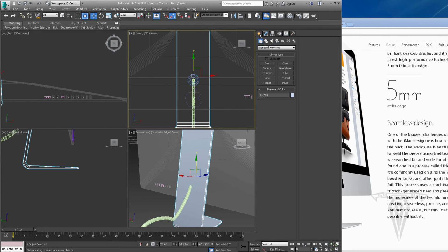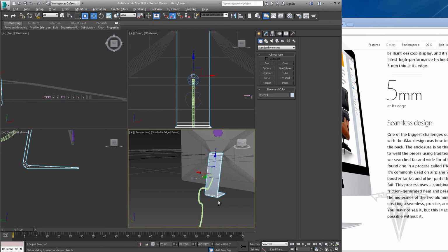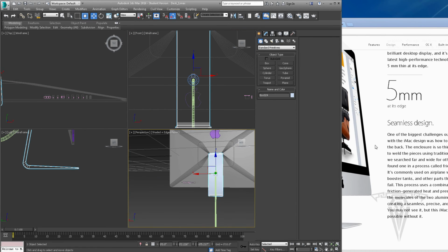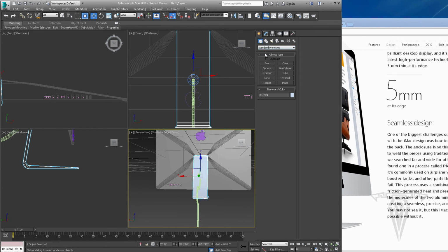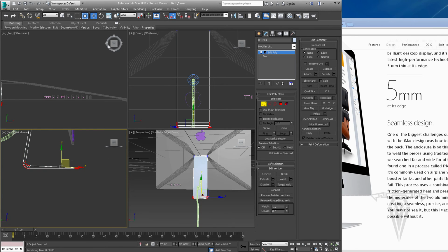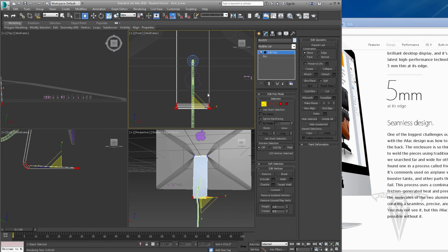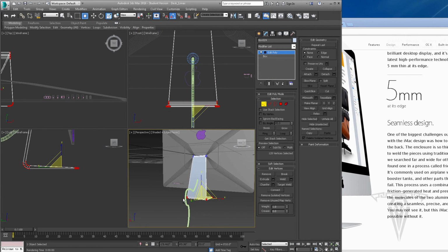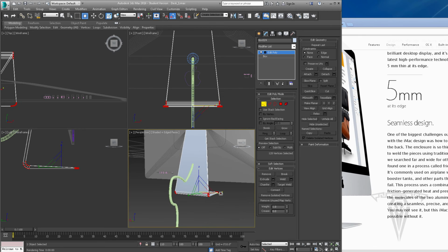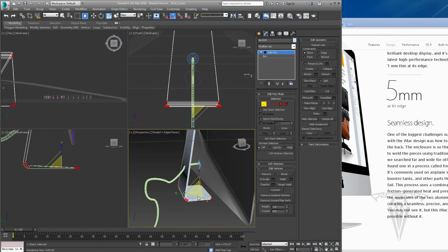Easy, just like what we did before with the front monitor. And man, I almost forgot. The base here is wider than the top. It's like a pyramid. So let me go to my modify panel, select these vertices down here, use the scale tool, and just bring them out a little bit wider. There we go. Wow, I almost forgot about that, but luckily we can fix it.